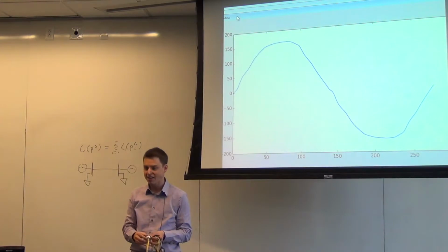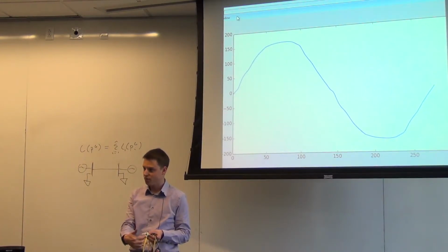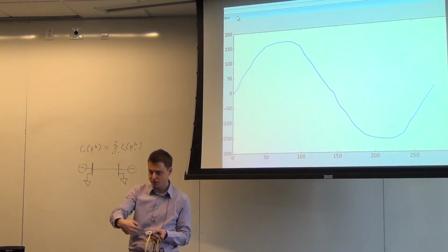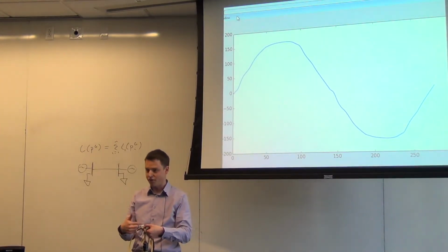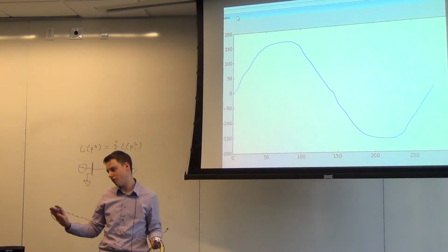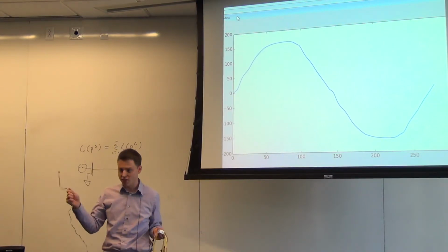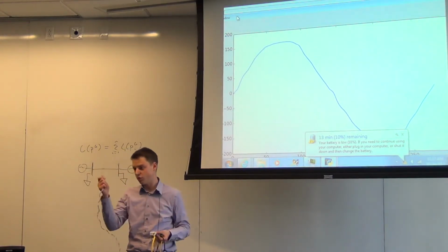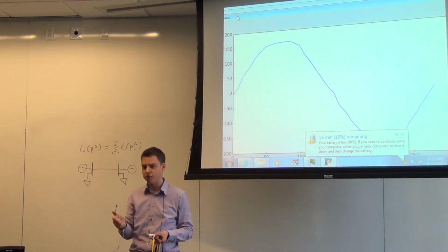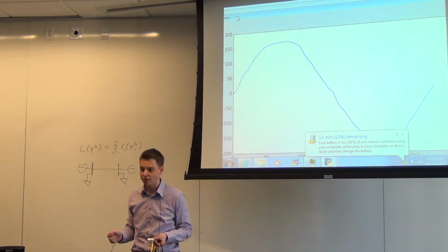It is a magnet that goes around this thing. And an AC current, this is sort of a current that's oscillating back and forth through this, creates a magnetic field here, which creates current or voltage differentials in this wire itself. So essentially current here will translate to a voltage difference here, and we're going to read this voltage difference using my A to D here.